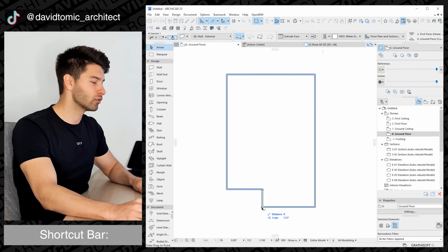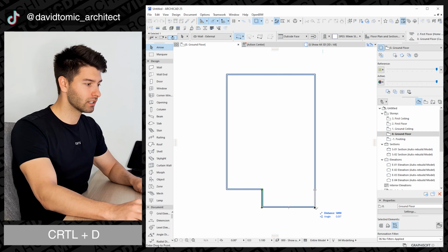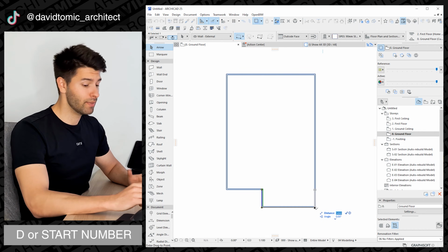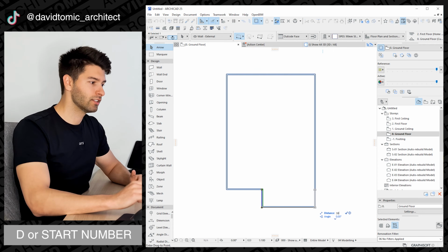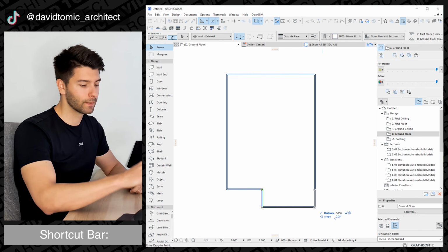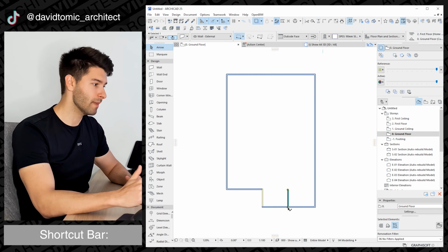Next, we can press Control or Command D to be able to actually move that object, run it all the way across this other wall. And let's say that's going to be a bedroom instead of a main living. So we'll reduce that to 3 meters from that wall to that wall. And by simply pressing the minus button at the end, it'll automatically do the maths for you.